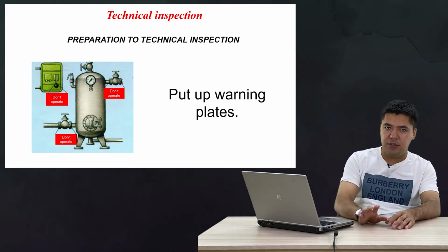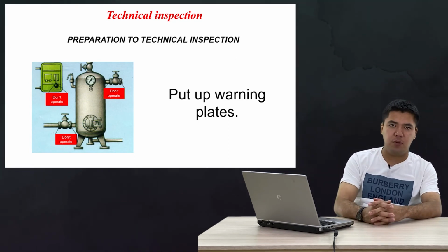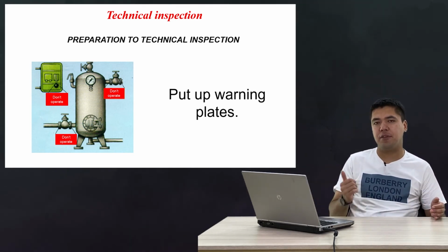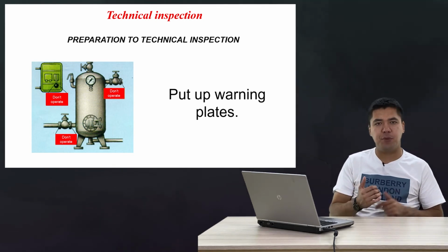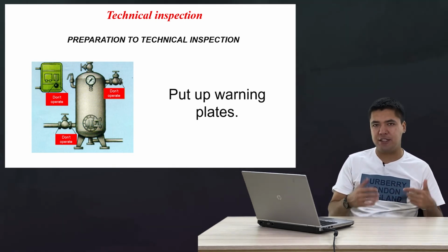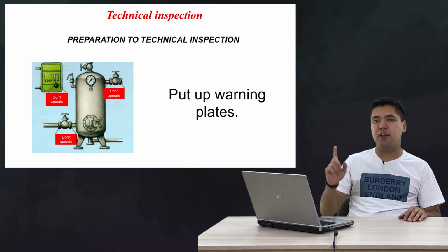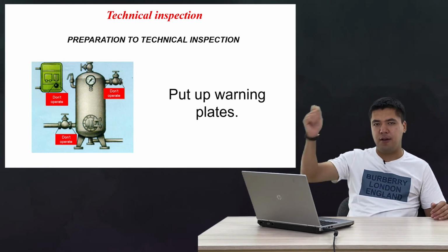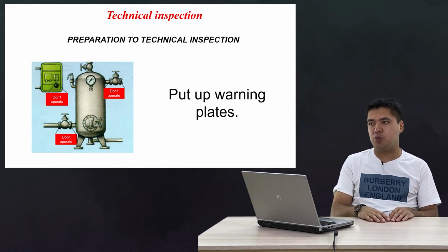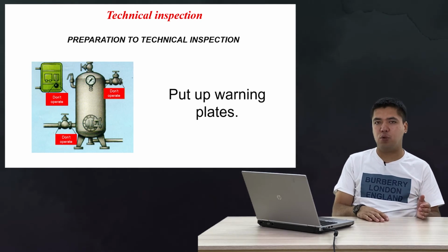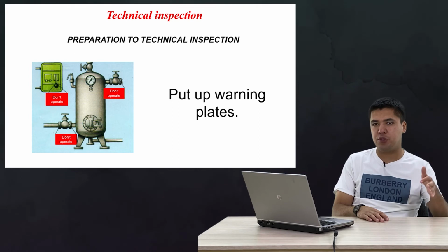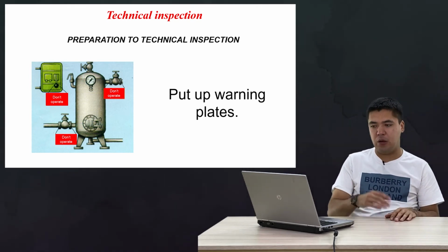And in modern life, when we shut the equipment and disconnect it from other devices for maintenance, repairing, construction, reconstruction, or inspections, we need to let other people know about such activities in process by putting labels. There is a process which is called lockout and tagout. We need to install locks, and after providing the inspection we can take the locks out.